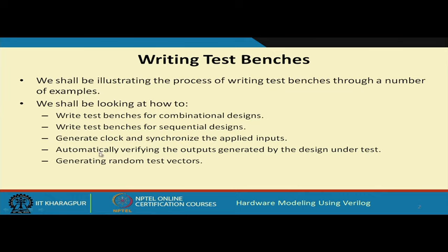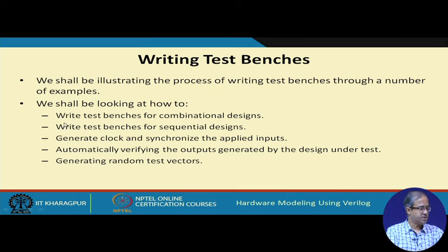Specifically, we shall be looking at the following things. We shall see how we can write test benches for combinational designs. Not only that, how we can apply the test patterns, how we can generate the test patterns. Then similar things for sequential designs. Generation of the clock and synchronization of the inputs is very important, how we can do that.